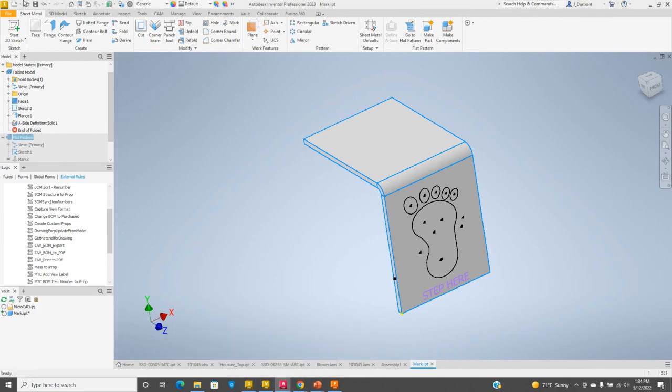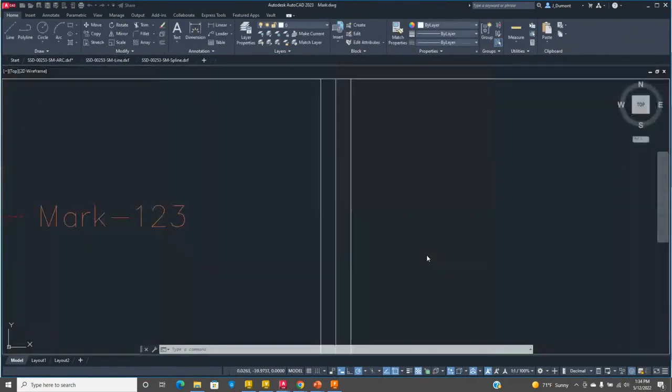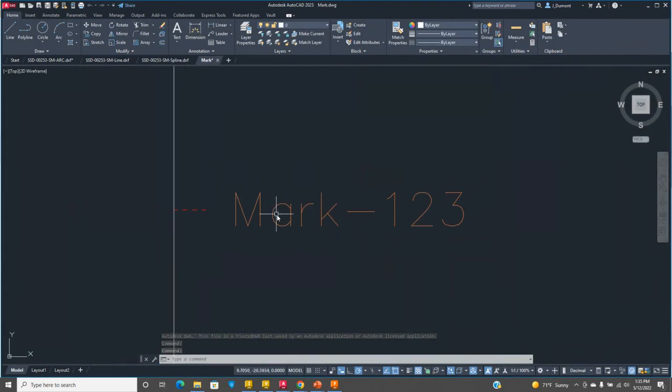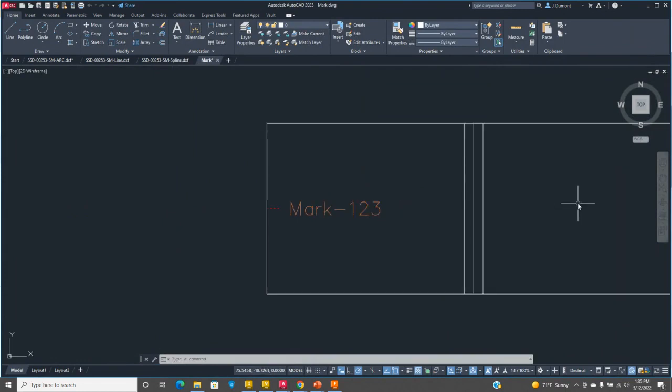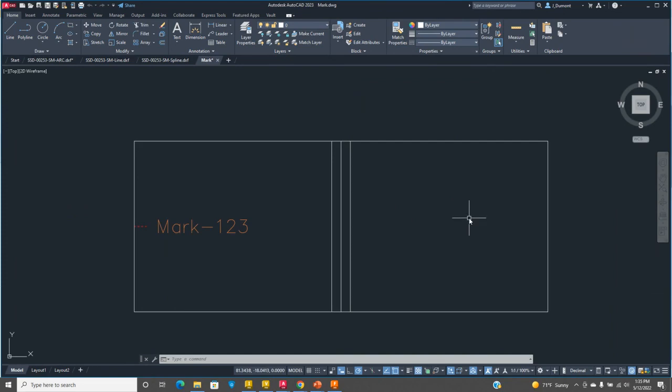If everything sounds good. All right, so now if I open this guy up in DWG, you can see that the layer, the color, the lines, everything is there. I didn't see the other part of it because I closed the file without saving, so my footprint is not there. That would have been a surface. It has its own color and line type. So that's what you're getting when you do a save copy as from the flat pattern versus selecting the face and then doing export face as. They are different commands. Okay.